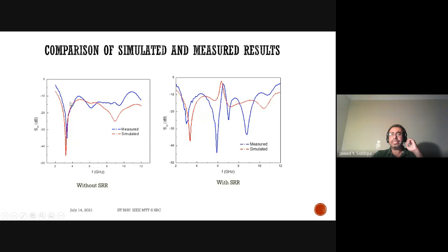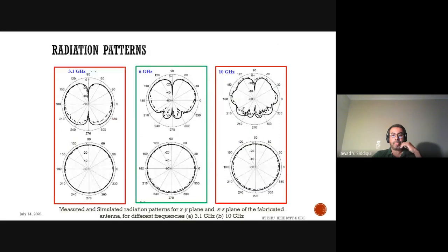This corresponds to the resonance frequency of the SRR. So you design an ultra-wideband antenna, you design an SRR separately, you place it strategically on the antenna, and depending on the SRR resonance, the dimension of your SRR or subwavelength resonator will yield a notch frequency in the whole desired band of the antenna.